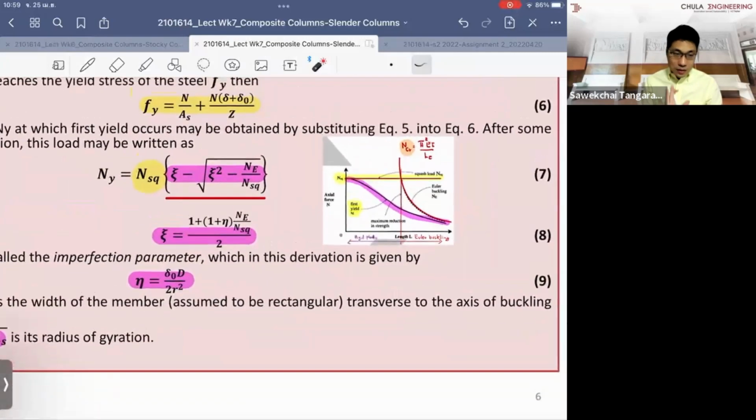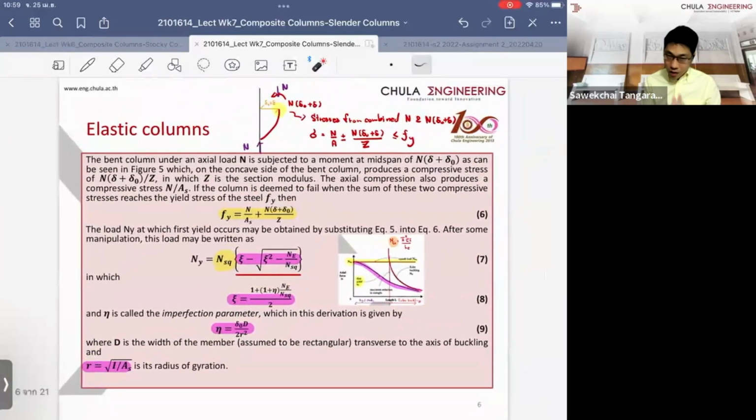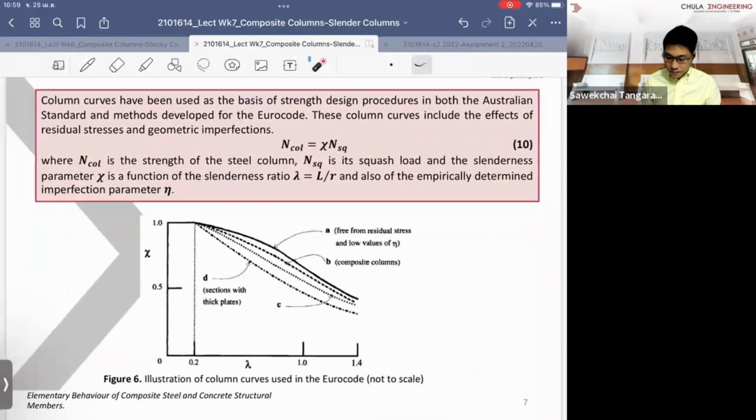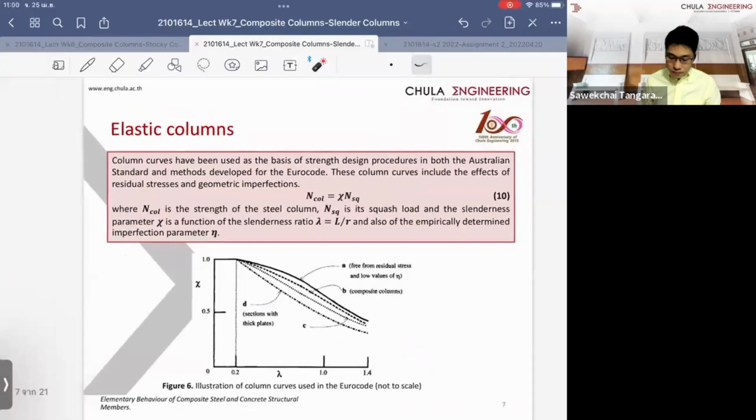That's why we can approximate the linear buckling capacity by using this line, but of course this is quite conservative, because we didn't use the capacity up to the fully rigid plastic. We just use up to the elastic, the first yield of the column. And we normally don't use this one in the code, but we have it to explain.